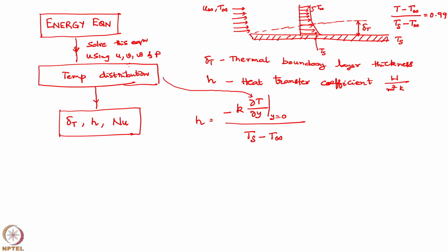So, what is the use of this heat transfer coefficient? What is this K? K is Kf. Kf is the thermal conductivity of the fluid which is flowing on the plate, not the thermal conductivity of the plate, please do not get confused. Ts is the temperature of the plate, T infinity is the fluid temperature, which I have told already. So, what is the utility of this h? That gives me the resistance to the transfer of heat